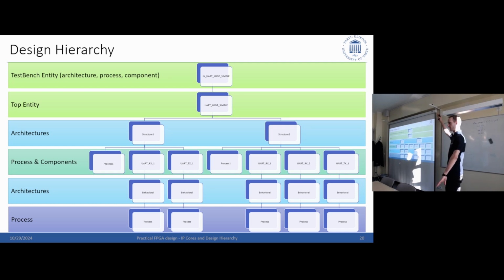Otherwise, you write a huge architecture and you realize, oh, I can split it up, and then you have to rewrite it. And especially as VHDL writing is quite slow, and simulating in the process of that is, well, let's put it this way. The time you can save here by thinking beforehand about how you set up your design is much, much higher, the time efficiency, than in other programming languages where you can just try it out and you copy it and you put it somewhere else. And just because of the simulation effort and everything. And also something more complex to simulate will take longer to simulate. Also to verify and those kinds of things, of course. The smaller your entity, the much, much easier it is to simulate and verify it.